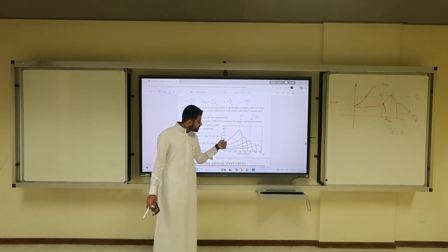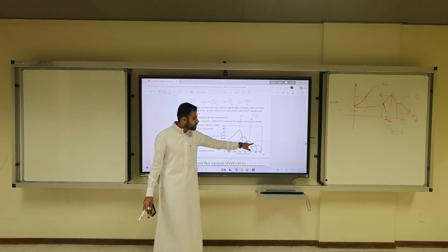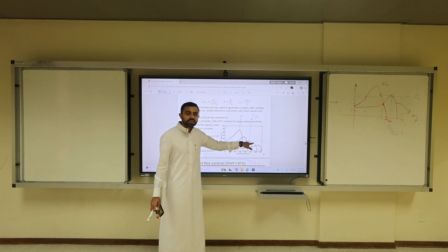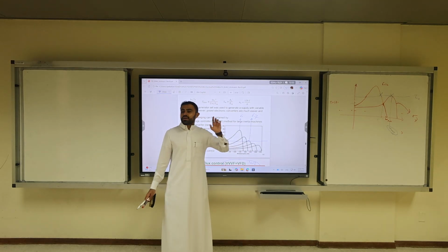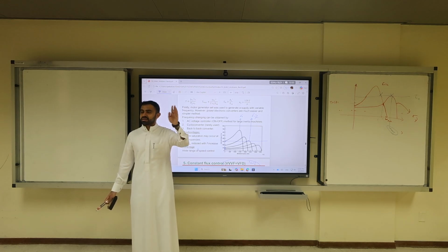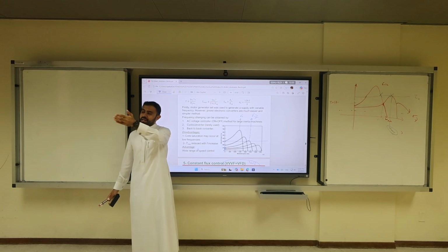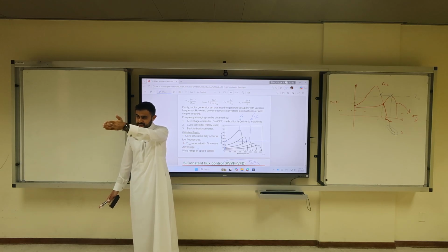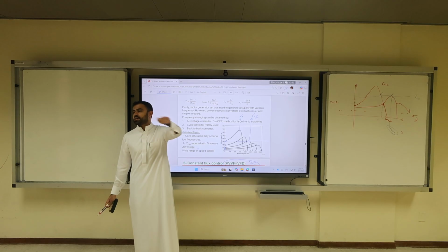For the 60 Hertz, the load would spin initially from 0 speed because the starting torque is larger than the load torque. You understand that? Yes. The problem is with these two curves, maybe 70, maybe 80, they will never drive the load. Because if the starting torque is less than the load, the machine stays stuck until you reach the maximum. This is class A and B. That's why we need class D and C to start moving from low speed.